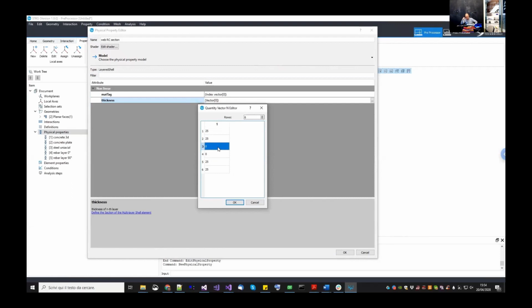Now the problem is, what is the thickness of this layer? You have to find an equivalent thickness. Now in this case, we have, in this example, we have a 6 diameter rebars placed at 180 spacing. So here the equivalent thickness would be the area of one rebar divided by the spacing, which in this case it turns out to be 0.175.